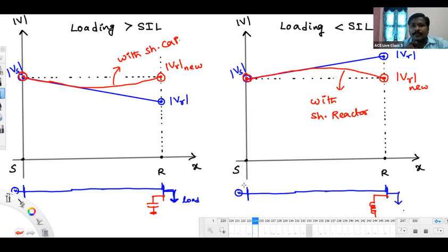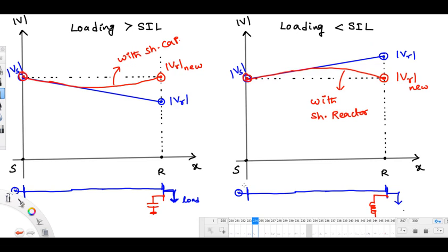Okay, sir. Another doubt, sir. While calculating the charging current, we know the formula is V divided by XC. Somewhere I read that to find XC, if the transmission line is single phase, we take the capacitance value as CAB, and for three phase, CAN. Is this correct? Per phase, yes. In a three phase transmission line, we take C per phase for the charging current. In the case of a single phase line, you should take the line to line capacitance. Okay, sir. Got it. Thank you so much, sir.